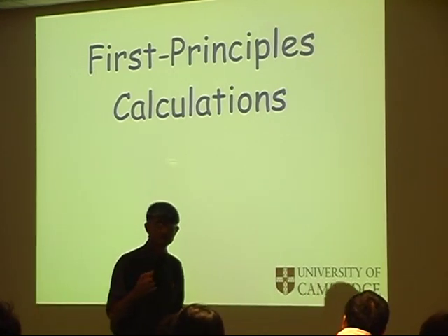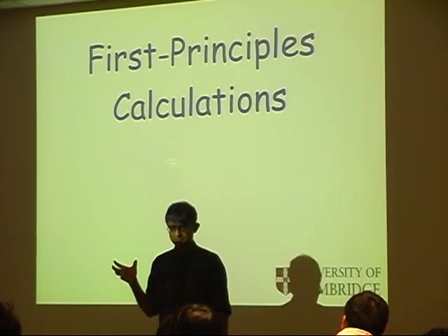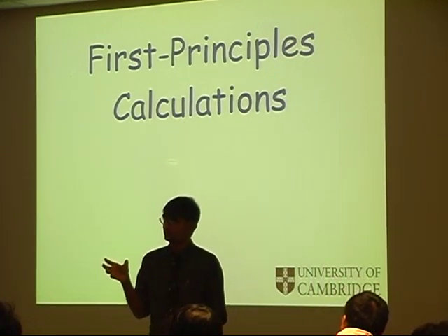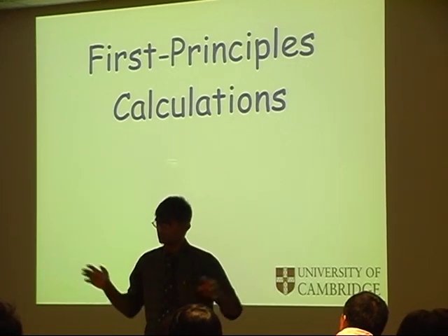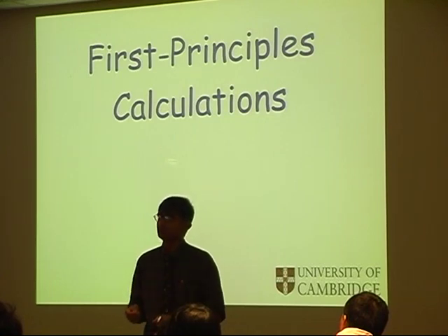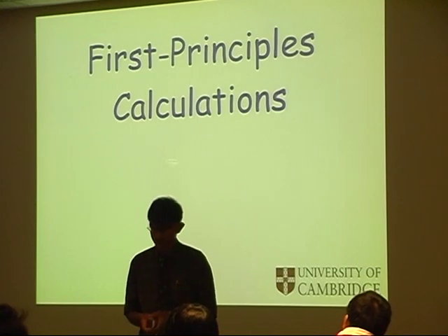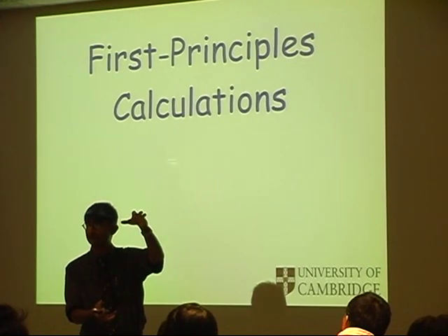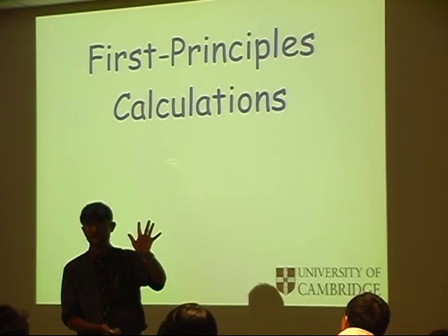Now, the big limitation of electron theory is that you can only deal with small numbers of atoms. So, for example, you can deal with ordered compounds. But if you want a disordered solid solution, then maybe the size of the cell becomes so large that it's impossible to do the calculation. And you know, the problem won't disappear if you have more powerful computers. You will always have a limitation on the number of atoms that you can treat. Okay. And when you're looking at differences between the free energies of alpha and gamma, the inaccuracy might be larger than when you're calculating for a single phase.